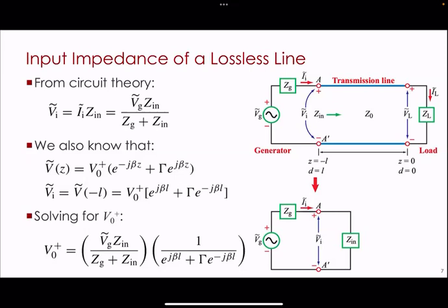And this is what we said the last time, where now that we've taken into account the transmission line effects in Z in, we can just treat this like a circuit problem. It's a voltage divider. So it's easier to think about it if you replace these with resistors, and maybe don't consider that as a phasor or something like that. Then it's just some voltage source and 2 series resistances, and you want to figure out what the voltage is across this resistance. Well, you would just do your normal voltage divider stuff. So you would do this one divided by the sum of these two multiplied by the voltage over here. That's how much of this voltage would be appearing across this load. And that's what we have up there at the top left. VG, Z in over ZG plus Z in.